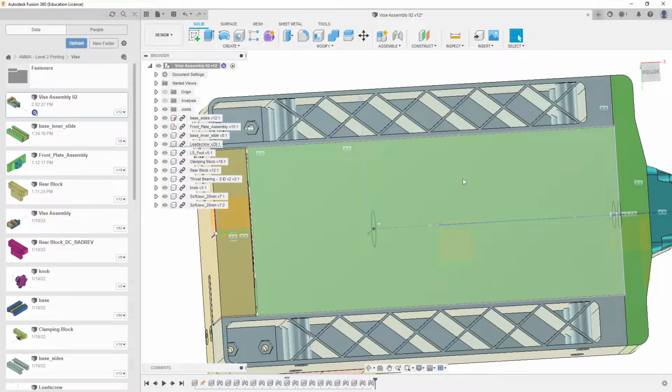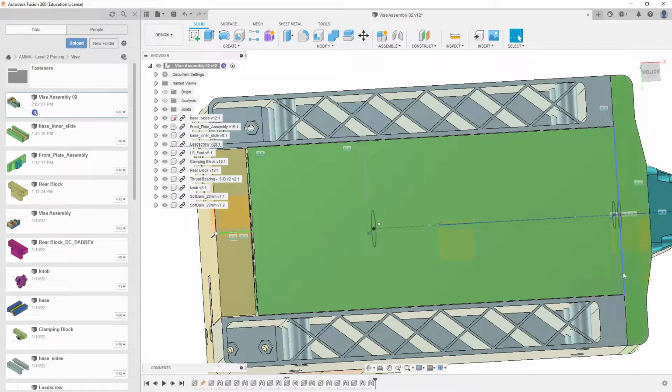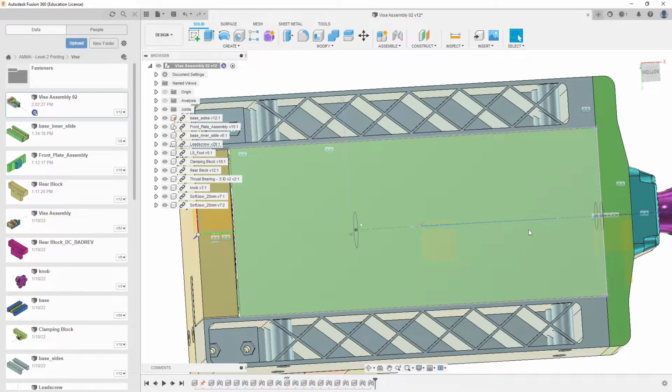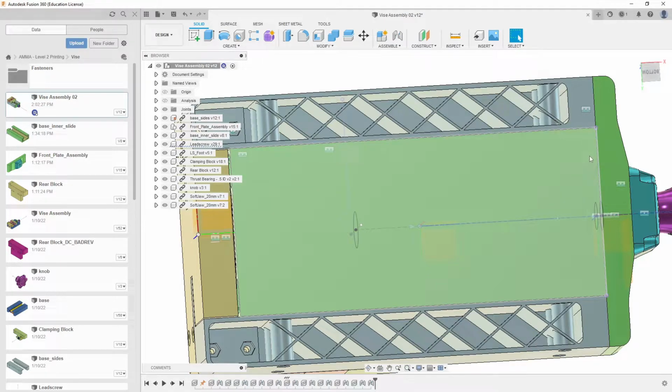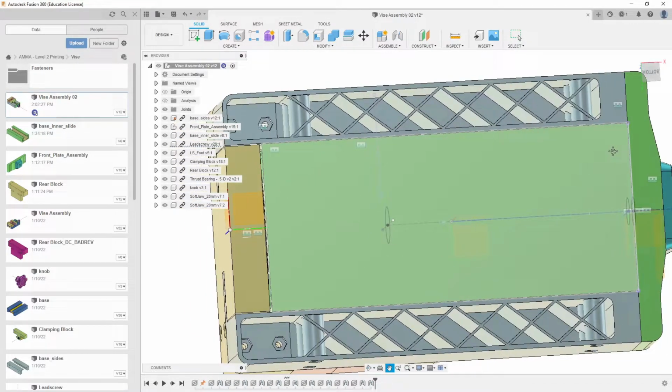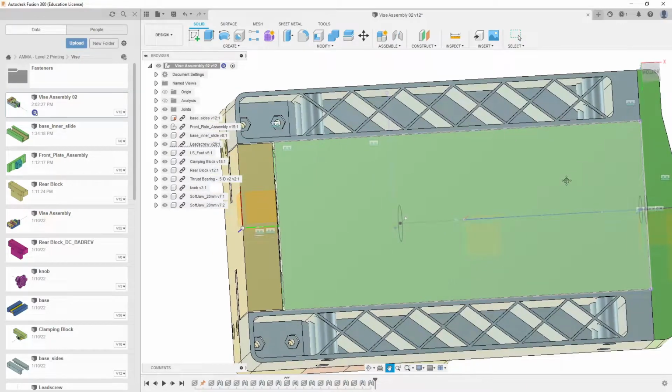By the way, that might mean that you have to sand it down. So hopefully you have some sandpaper, like a 120 grit or something, that you could put on the table and run it on it and try to make this surface nice and flat. If there are any extra extrusion bumps, because depending upon the way you printed it, that bump, if it's half a millimeter, it's going to be a problem.